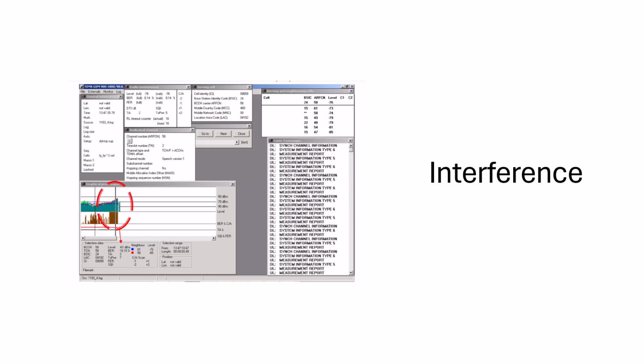External interference: non-GSM devices, illegal repeaters, or industrial equipment can create noise on GSM bands, disrupting service. Operators mitigate GSM interference by selecting an appropriate frequency reuse pattern, optimizing power levels, adjusting antenna tilts, and performing ongoing drive tests or frequency scans to identify and resolve interference sources.